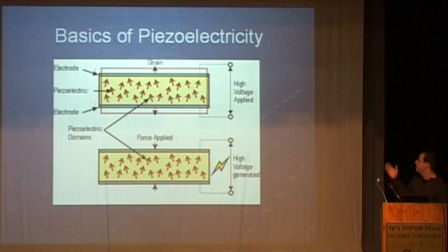So this is the basics of piezoelectricity. I don't think I need to explain much, but when I apply high voltage, I can create strain in the crystal, and vice versa. When I create strain in the crystal, I can create voltage. One of the best ways to measure piezoelectricity at the nanoscale today is piezo force microscopy, which is based